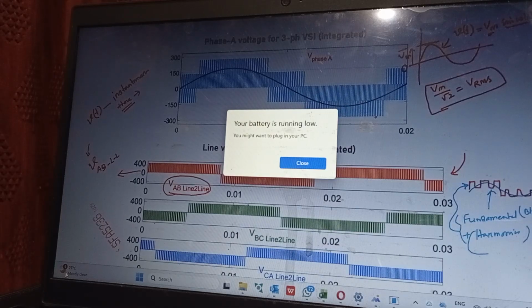Both of them together. So simply think about it. You have some milk, you have some water. If you mix them up together, that is that red colored thing, which is generated at the inverter output. If you can separate out the milk, let's say the desired component, that is the concept. That milk part is the fundamental component. So for torque production, for power delivery, etc., this fundamental component is more relevant. Again, these are a lot of fundamentals inside. I don't want to go deep into it. It will take another 3-hour lecture. So just simple term, think about this milk and water analogy mixed together, right? Desired thing and some unwanted things together. Let's say you want only milk, so adding water is unwanted, right? That is kind of harmonics here.